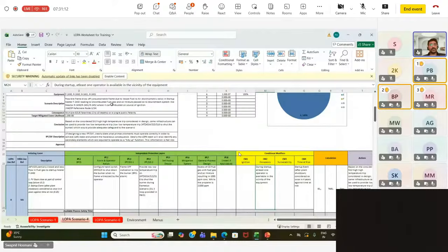So then that flame will go off, and then this fuel or partial fuel gas will essentially be mixed with the air, because you have combustible air. So this is forming a combustible mixture, and this is again passed on to the downstream reactor, okay, where it can combust when there is a source of ignition. Okay, so this is typical to the earlier case, but in the earlier case there was more air and that was blowing off your flame. In this case, there is partial fuel gas which is not allowing the flame to sustain, and that is why there is a flame blowout.